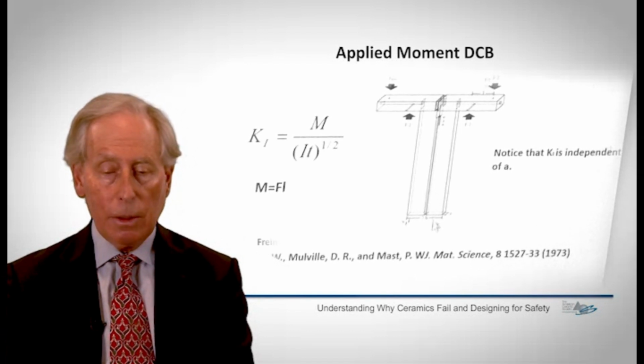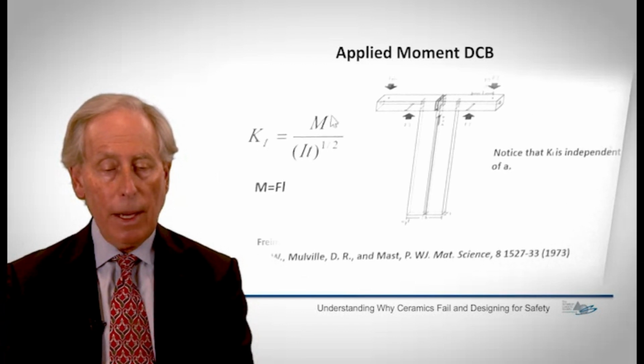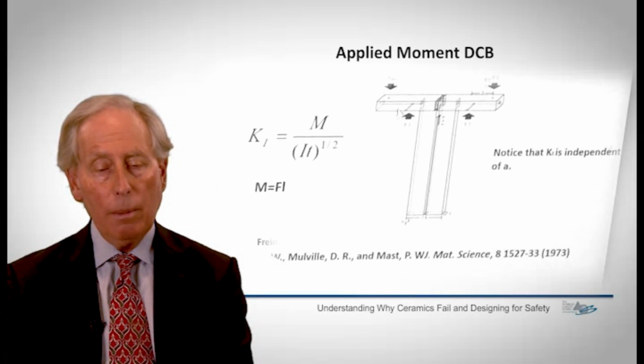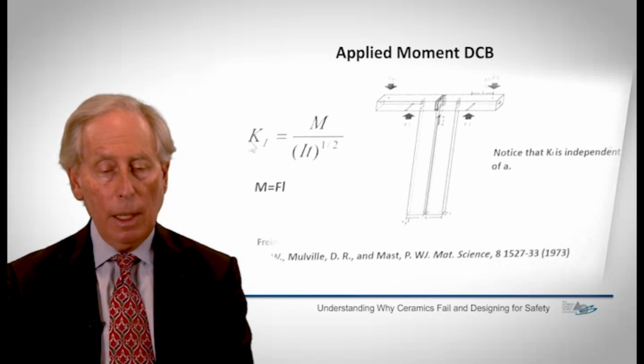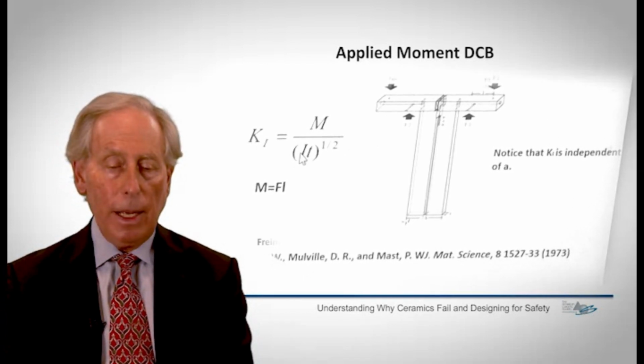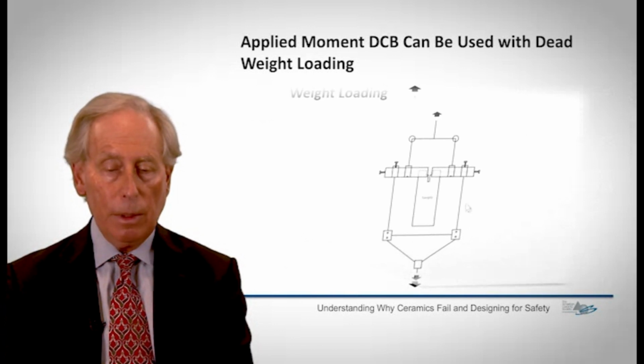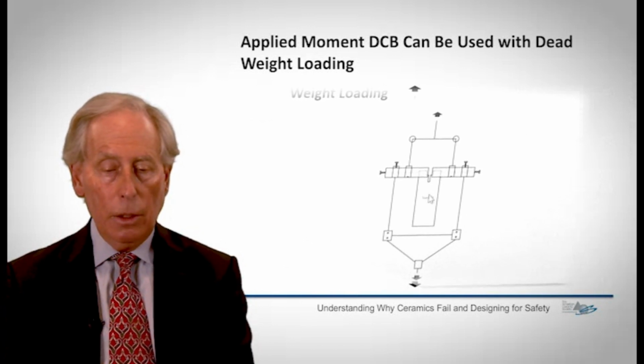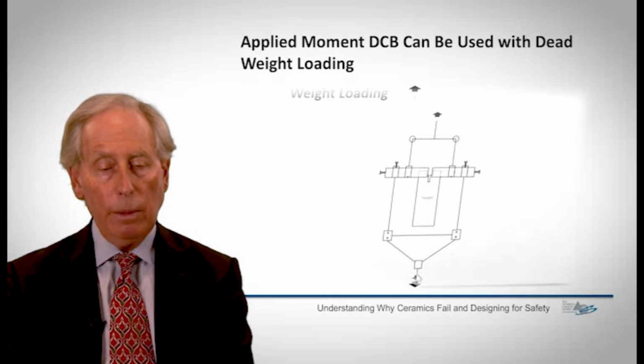Again, one requires a groove down the center of the specimen, but here the stress intensity factor is no longer dependent on the length of the crack. It's depending on the moment arm that we apply to the specimen here. So we bend these arms in some fashion, I'll show that in a moment, and the stress intensity factor at any point is related to the moment of inertia of each side of this cantilever and the thickness of the specimen T.